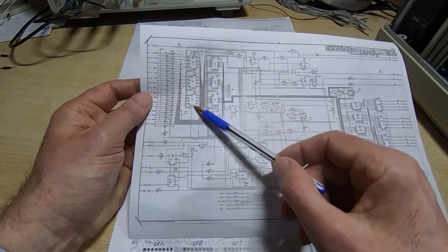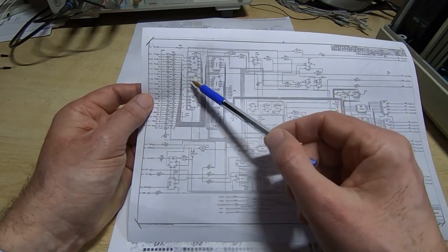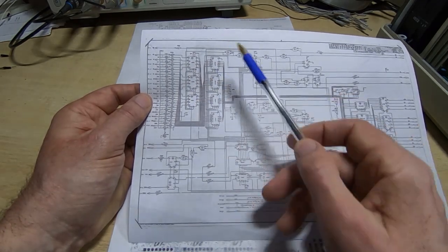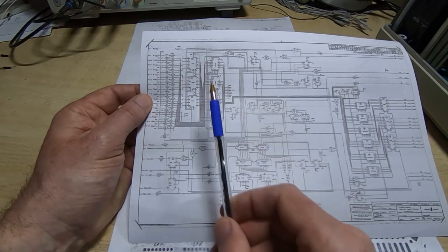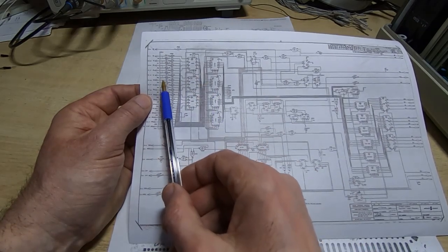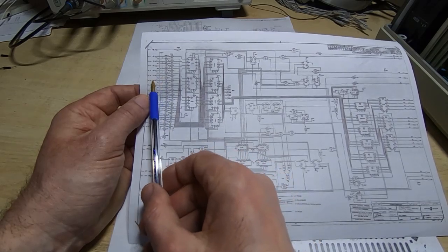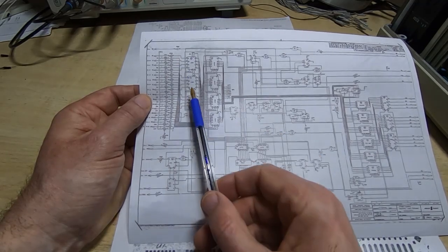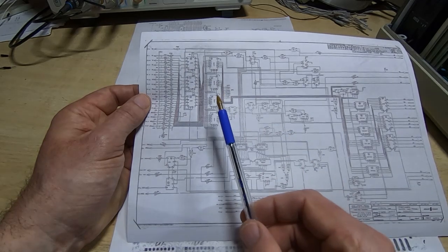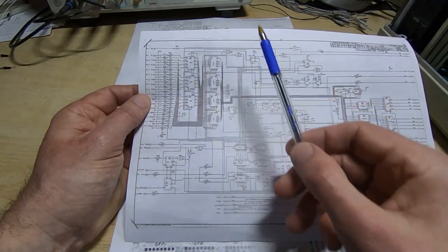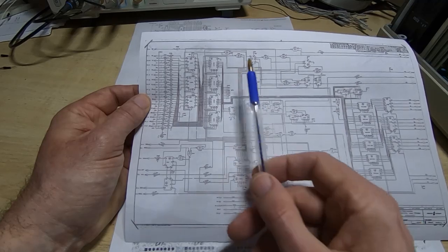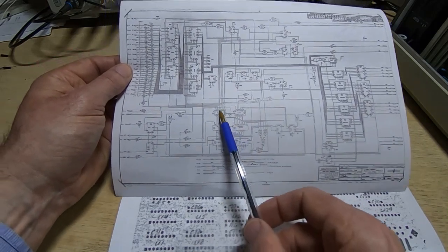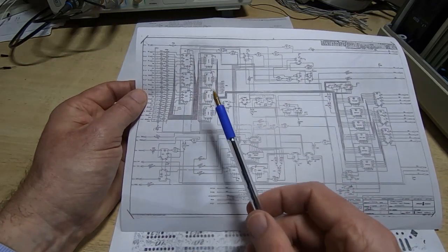And that's where I initially thought the fault was going to lie in this. I thought one of these counters had failed. So the way this system works is these count to the next address that's required. That value is fed out to the PPU. The PPU obtains the next data value from that address and then feeds it back into this system. It comes in as a 16-bit value, and that comprises either 2 characters or a character and some status bits that are used to control how the character is displayed. When the data is fed out, the value is incremented, it's controlled from the state machine, and then the next byte, or word, is obtained.